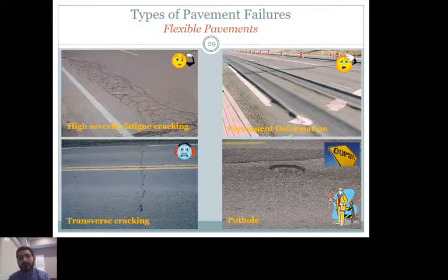It's a problem that's highly significant in rainy conditions where we can see the issue of hydroplaning, which is when you drive in a rainy condition and there's water like this, you will be driving on a very thin film of water. That means there's not much interaction or friction between the tires and the roadway, and that's a very hazardous situation.